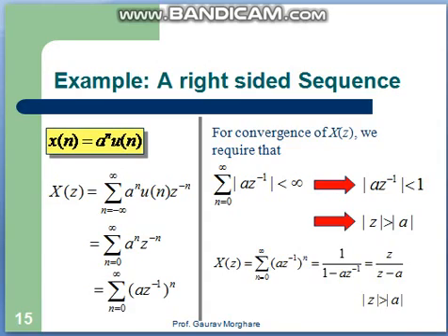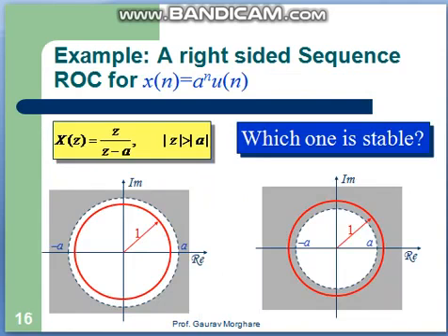So in this step it is easily calculated that if a to the power n u[n] is transformed, the Z transform answer will be Z upon Z minus a, and the ROC will be mod of Z greater than a. This is a stable system. Only the value of mod Z, that means Z should not be equal to it, should always be greater than a.